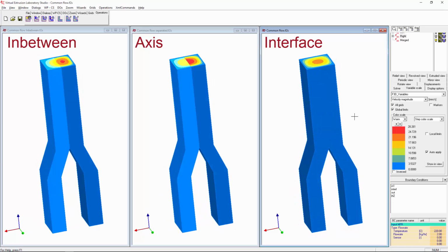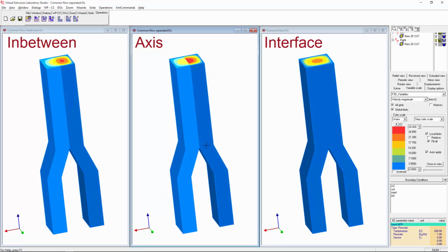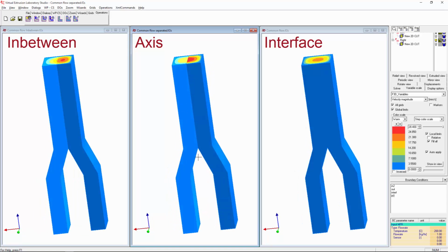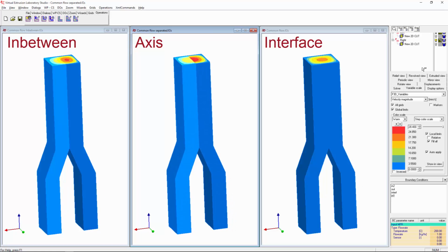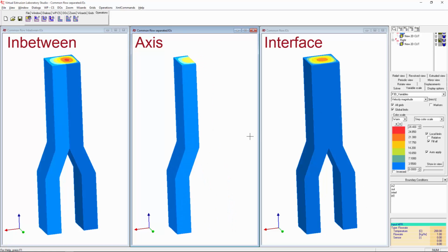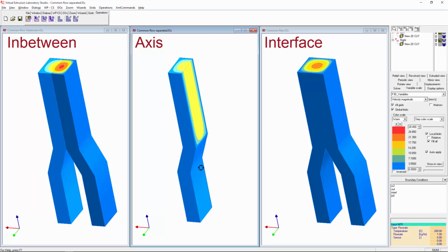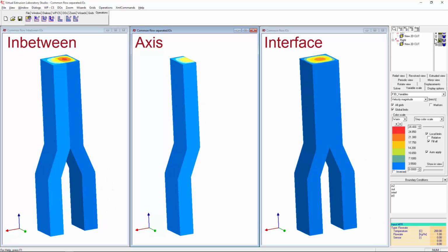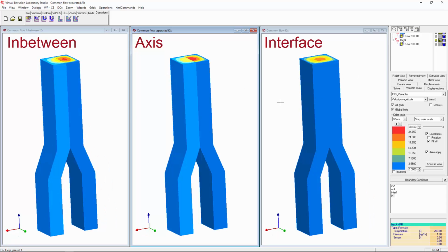So if we'd like to understand the coextrusion flows, we should use the interface in between. But also, I would really encourage you to use the axis or the perfect slip in case you'd like to just solve one polymer at a time, because we don't have to solve them together. Based on what you really need, you can choose one of these boundaries.